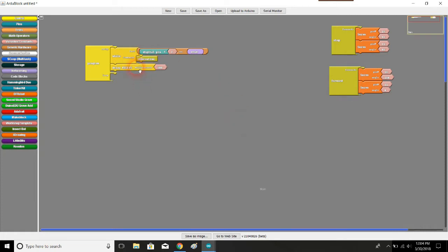So what I want to do is change that subroutine block to mirror one of the names I have here. For example, right here in this while loop, I want my robot to be stopped. So I should say stop. Now what this is going to do is say, okay, I want to find the subroutine that is named the same as this one, which is this guy. And then I just want to do those commands that are inside it. And since these commands make the robot stop, putting stop here is going to utilize those commands and cause the robot to stop.